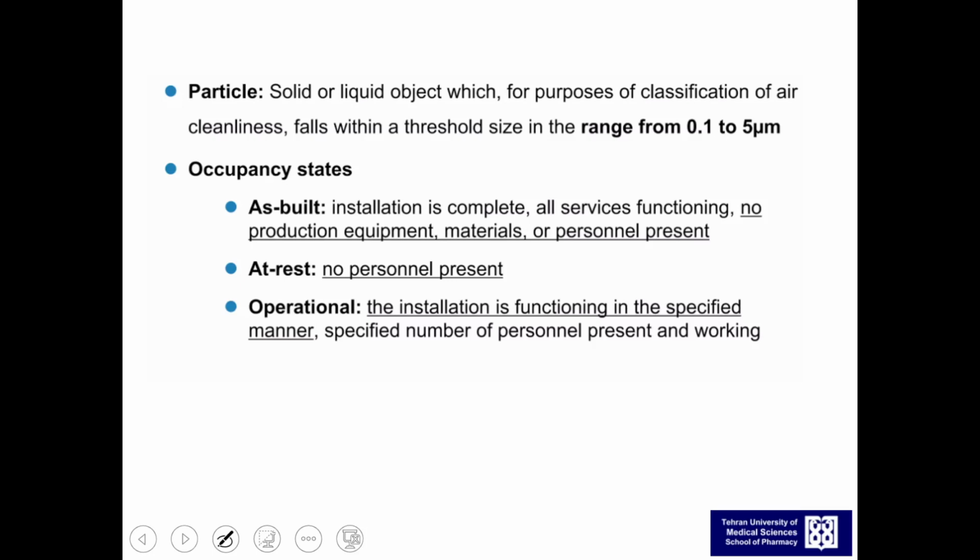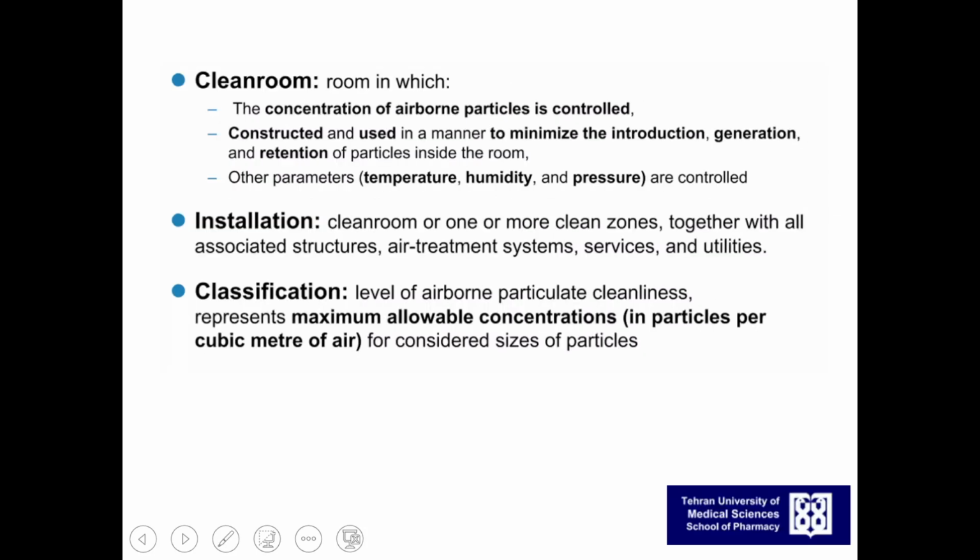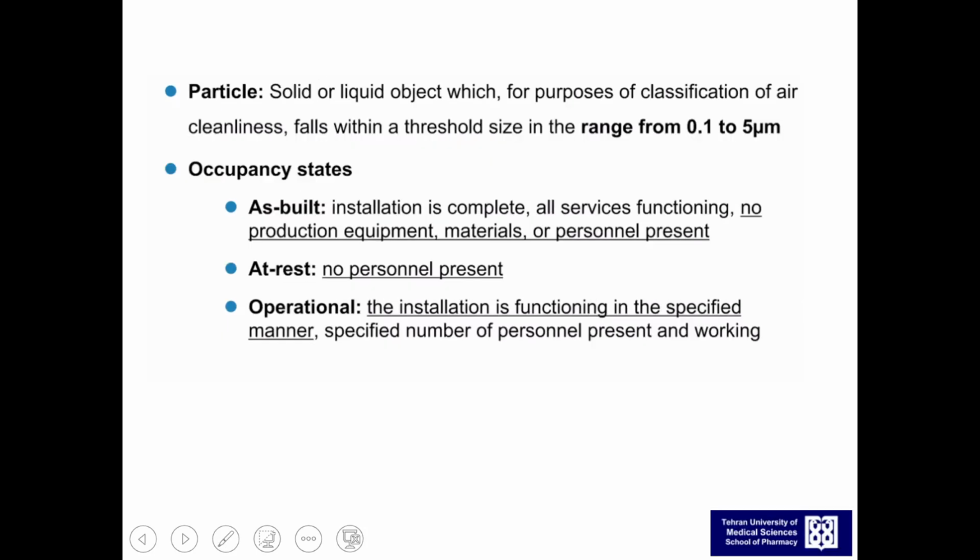The range of the particles should be 0.1 to 5 micrometers. Occupancy state: the installation is complete, all services are functioning, no production equipment or materials are present, and no personnel are present. In the at-rest state, no one will be there, only machines.